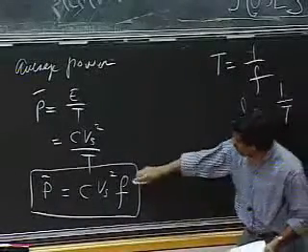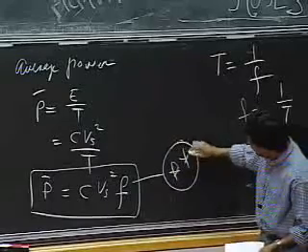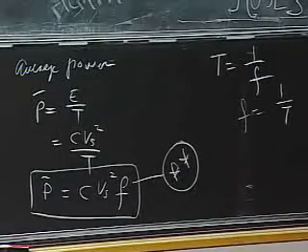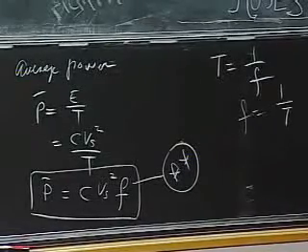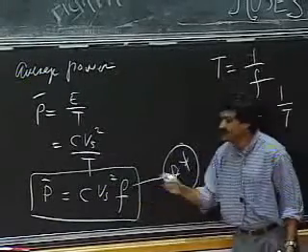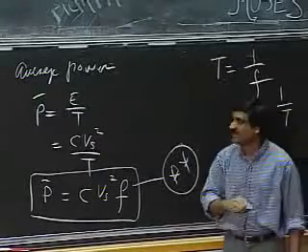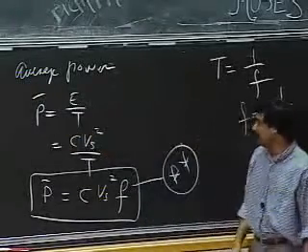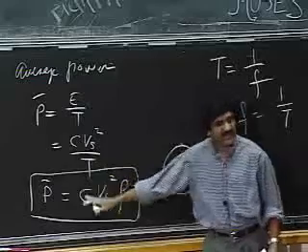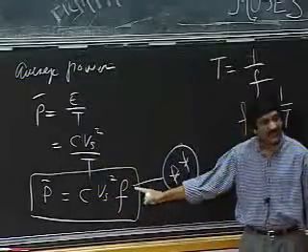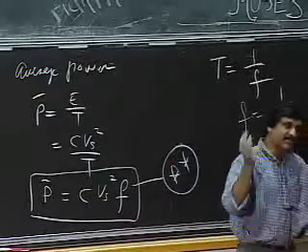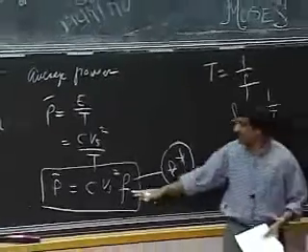So what does this say? Let me mark that as a thing to remember. The second thing to remember. One was the power that was the static power. And second is this power relating to this frequency F and the charging and discharging of the capacitor in that little circuit shown up there. So this average power is CVs squared F. What this is saying is that if F is high, if I have a high frequency of charging and discharging the capacitor, then I'm charging and discharging much more frequently, so I'm going to consume more power.